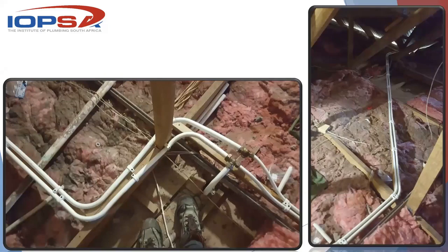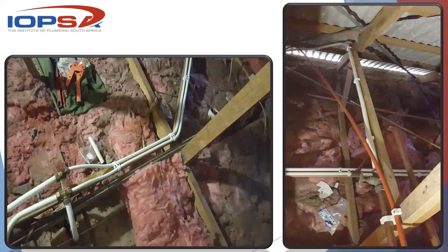And here are some examples of what you would want to see in a ceiling. If you get up into a ceiling, you look at this and you say, okay, all right, this is good. And now you can expect similar quality throughout the rest of the installation as well, which is exactly what you're trying to see. You can see there most of those pipes are 22 mil. On the left-hand picture, just to the right there, you'll see those T's are reducing. They go down to 1/2 inch to the right-hand side. But most of those are 22 mil, so those brackets will be 400 mil apart and nicely fixed against a piece of timber. Good, very nice, very neat.